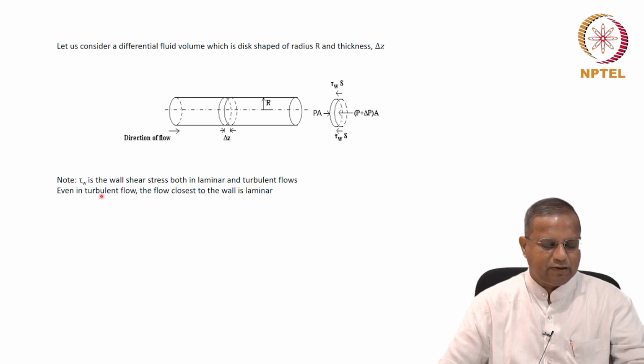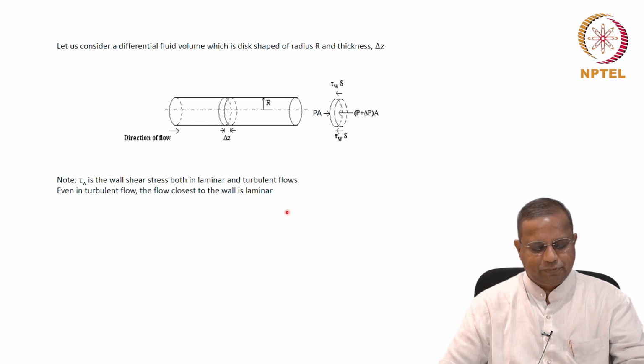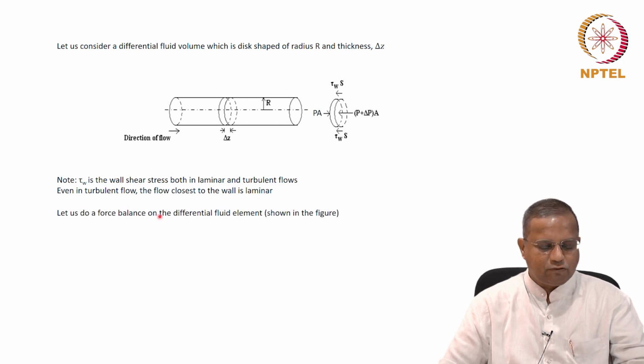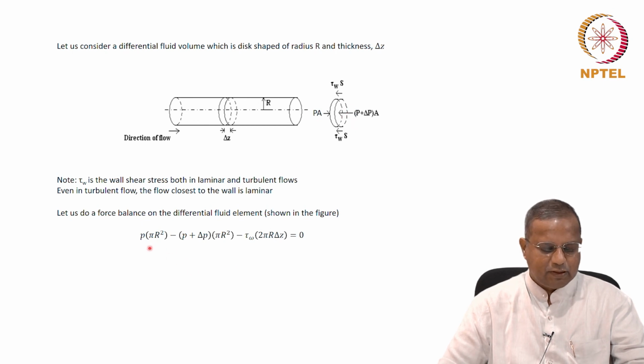That's what is said here. Even in turbulent flow, the flow closest to the wall is going to be laminar. So let us do a force balance on the differential fluid element that is shown here. And therefore, if you do a force balance in a free body diagram that was drawn for the purpose,